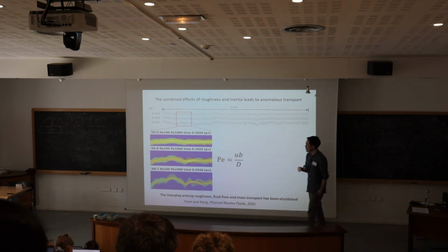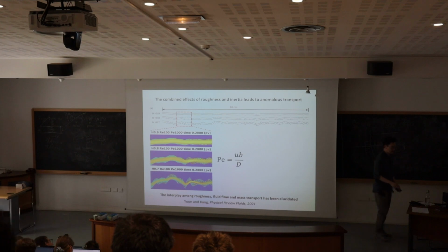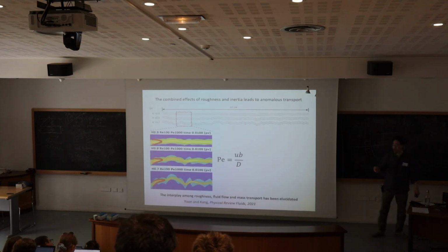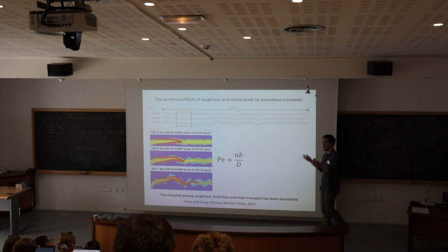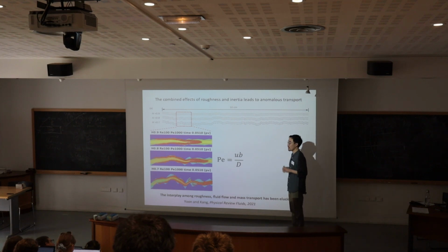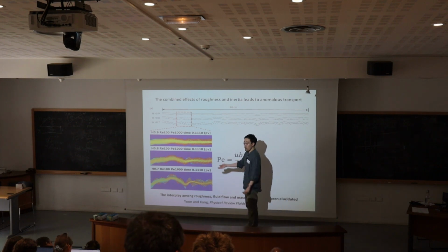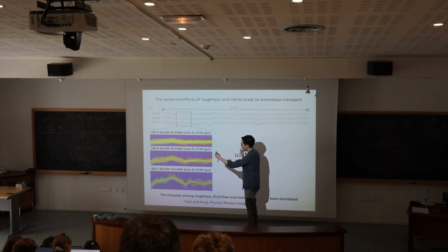So what do you see here at Reynolds 100, which is again the inertial laminar regime? Let's be clear that what I will be showing from now on is nothing turbulent. It's all weak inertia laminar flow. Also, the underlying flow is strictly steady state, so there's no time variance. As long as the boundary condition is fixed, there is no unsteadiness.